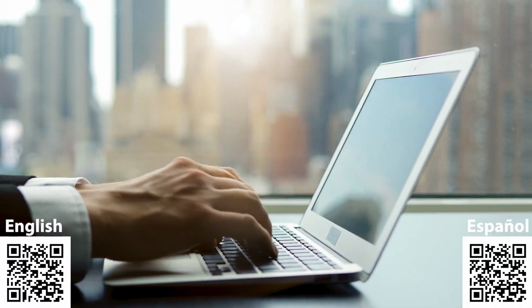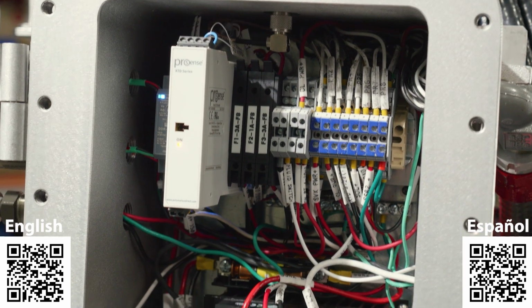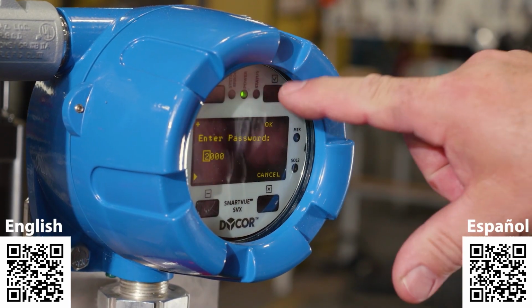Smart ESD allows autonomous control of the surface safety system. What that means is you can control it remotely from virtually anywhere in the world. It provides system diagnostics. It allows edge computing and cloud-based communication, so you can minimize the number of visits to the site to check on the health of the unit.